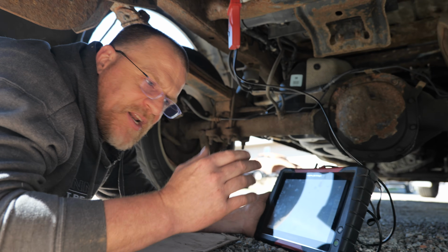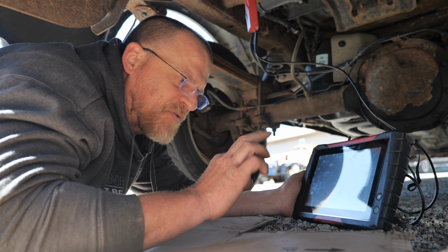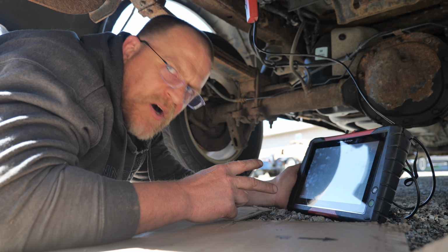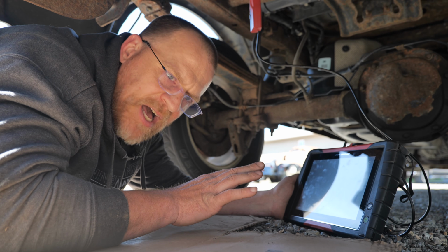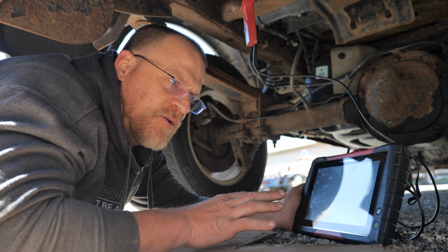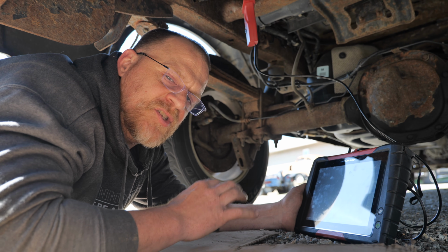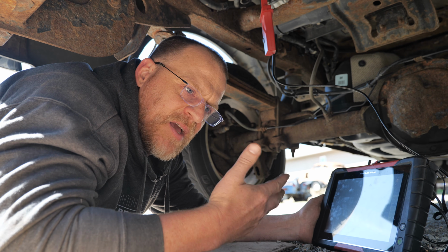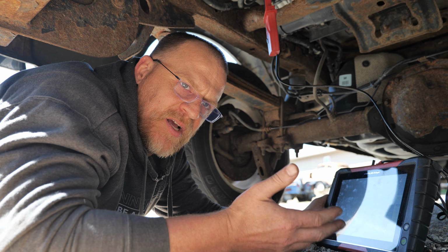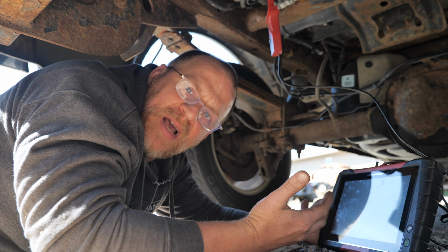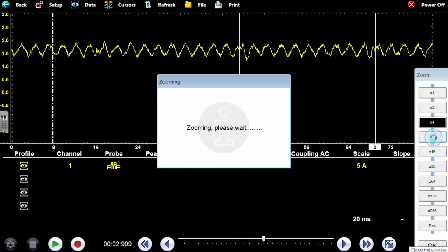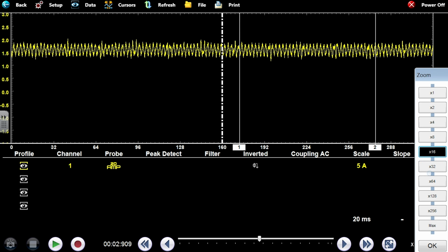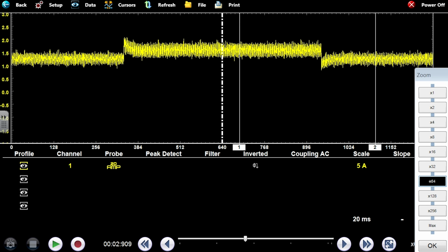You would have to drive it and then shut the truck off, and the pump would have to stop right in that dead spot for it to not start back up. And that was one where it would never die on the customer. It was only an intermittent no start. And that's why my question to Pete was so important right now. Is it dying on him driving it, or is it only when starting up? This is where my head was when I asked that question. But taking this waveform tells me, yeah, it's not going to be that. This thing probably did die on him when he was driving it, most likely. If we're in this area, it's not going to be a dead armature.